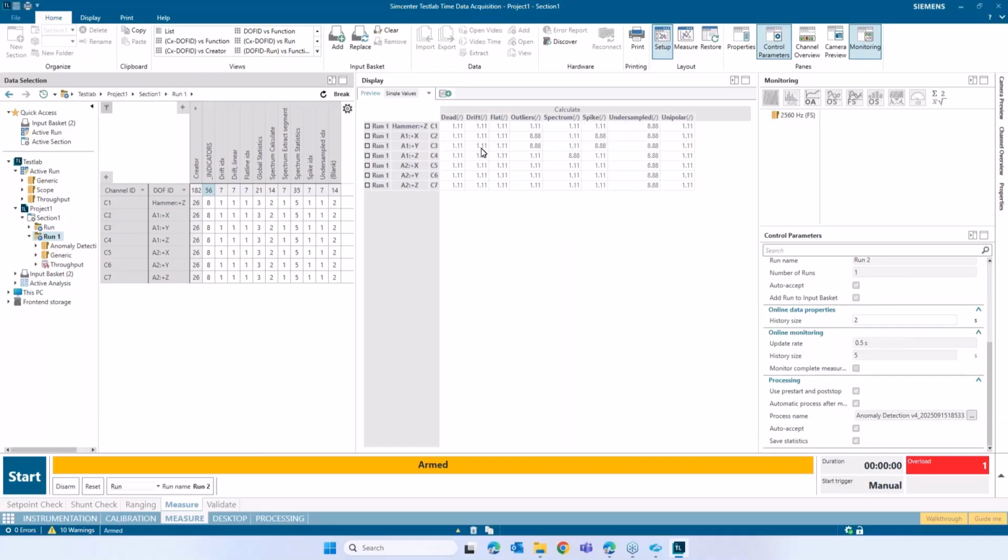In this case, I can see that the accelerometer X channel and the Y, which would have seen the spikes, are correctly indicating that there was indeed a spike. The other important thing is that the A2 is not showing any problem because it didn't experience any spike. Only the A1 accelerometer for these two directions detected that, should have shown there's a problem, and it correctly shows us that.